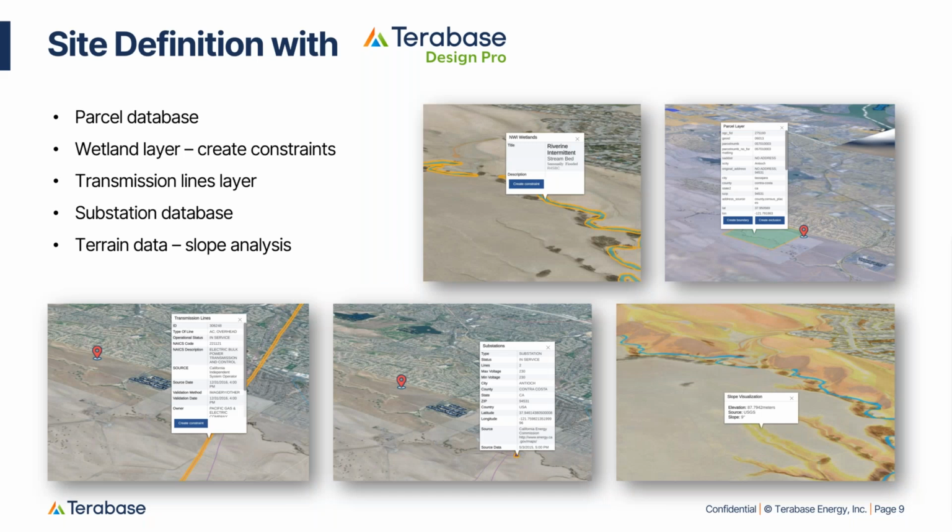Beginning with site definition, Design Pro has access to several GIS layers that can be very useful for informing your site plan. Starting with a parcel database, you can easily create a site boundary with the click of a button. Pull in a wetland layer to make sure that you don't place solar on top of a protected zone. See the energy infrastructure that's installed near your site, such as transmission lines or substations, and even pull in a high slope layer to identify if topography is going to be a challenge for your project site.